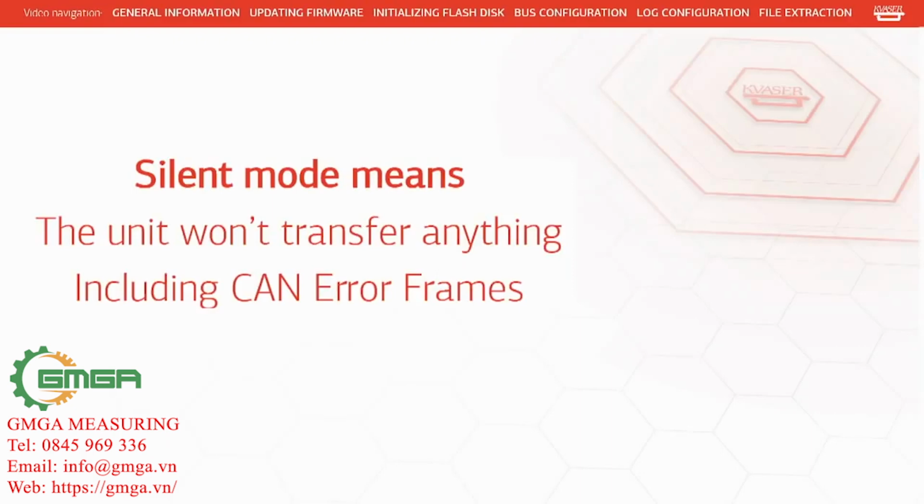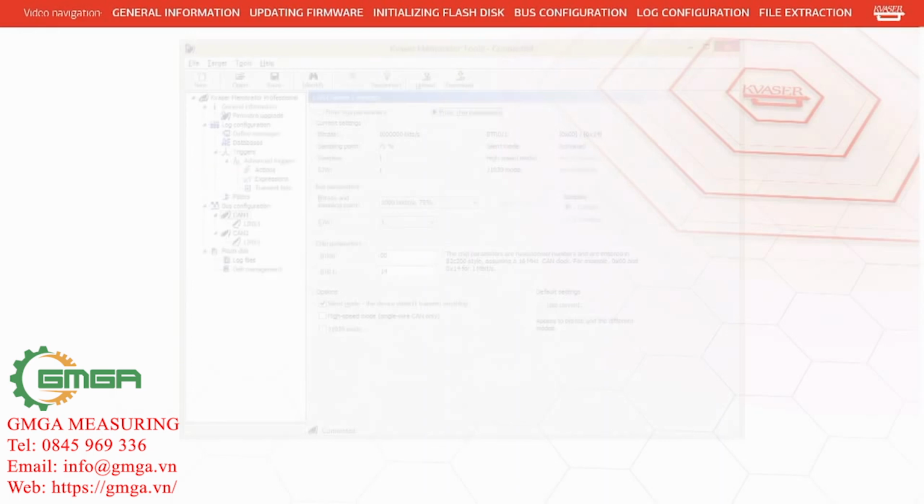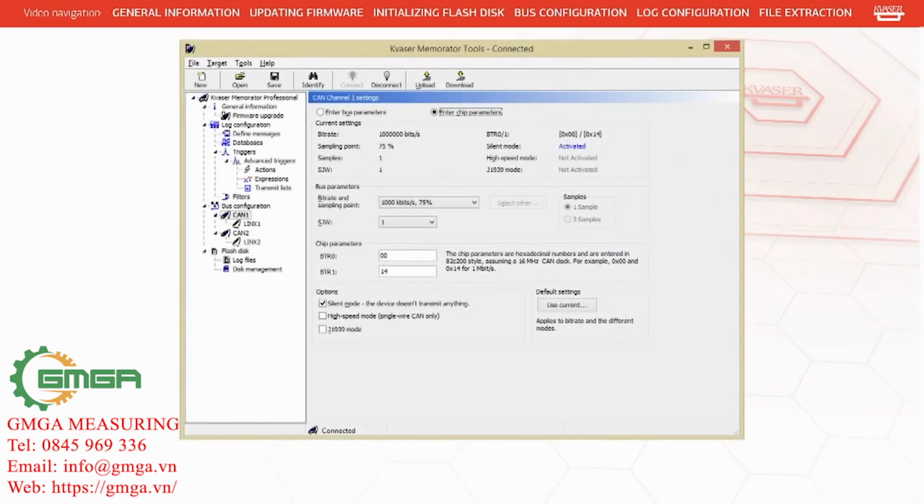system. However, CAN requires at least 2 active nodes on the bus, so if the system you are connecting to is a single node on the test bench, you must turn silent mode off. The Memorator will then be an active node on the bus, participating in standard CAN frame error checking. If you plan on logging data on both channels, be sure to configure the second channel's bus parameters as well.